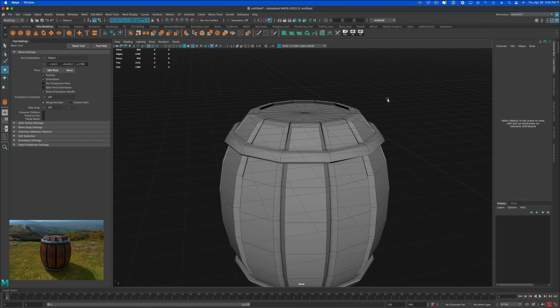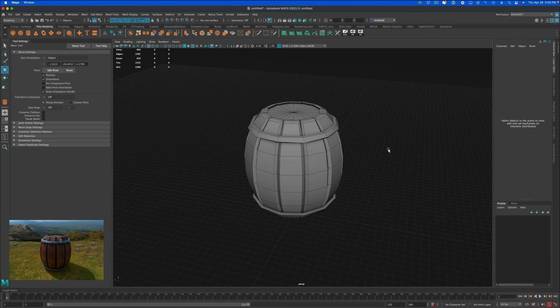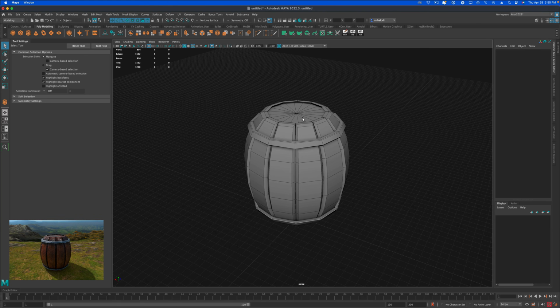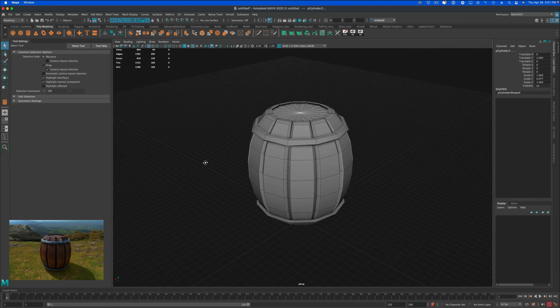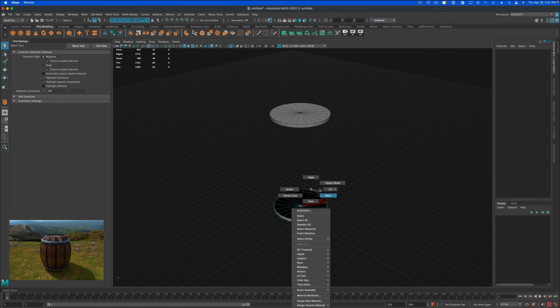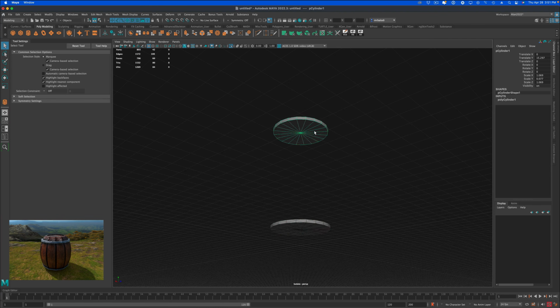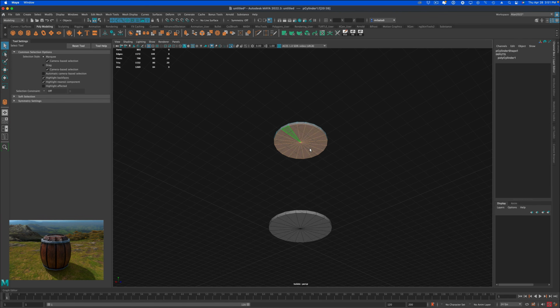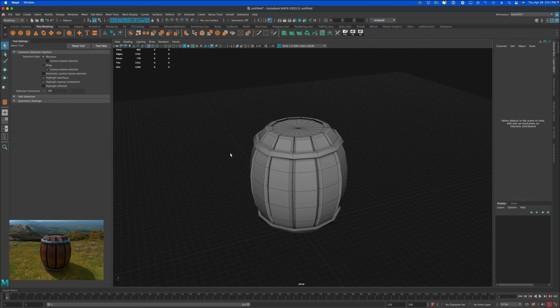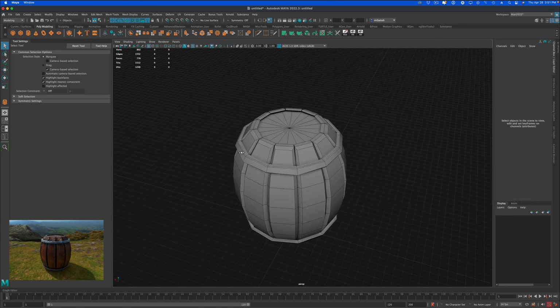Alright, next I realized that I obviously don't need the inside geometry of the cap, so I'm going to select both of them, holding down the Shift key and pressing the isolate button. Then I'm going to go into my camera, my selection, and turn on camera based selection, so I can just drag the selection around the middle pieces without selecting the back of my topology. So I do that here, and then I want to make sure that once I go into object mode that I uncheck camera based selection, because a lot of times if you leave it on, it will mess you up as you're modeling. So I like to leave it off when I don't need it.